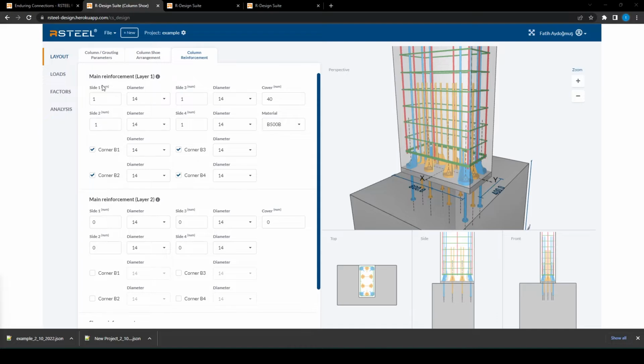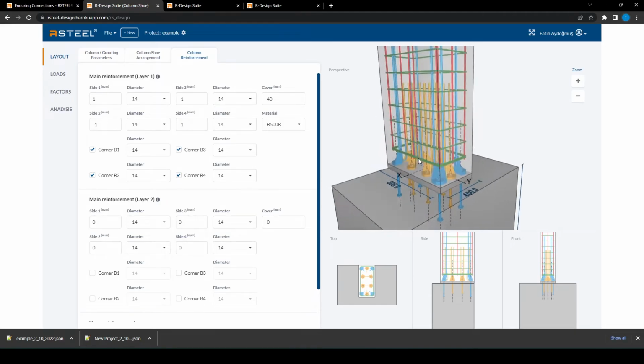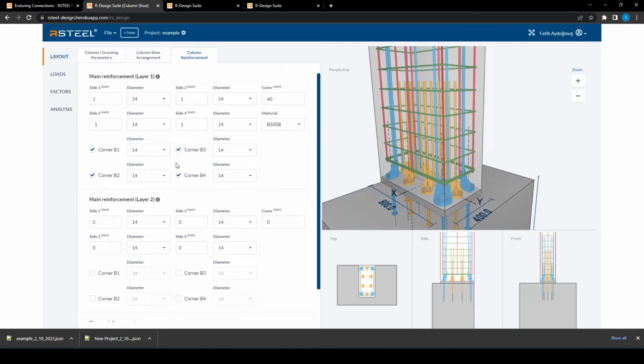Users may define the reinforcement in the column or they can skip this tab. Reinforcement definition won't affect the shoe calculation. The column reinforcement tab is prepared to show rebar distribution in the column with the shoe. Also, a column design check can be performed by the application if the user defines all necessary reinforcement. This topic will be explained in detail later under the title of the analysis page column reports.